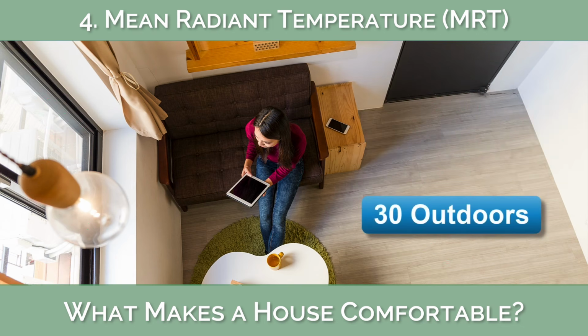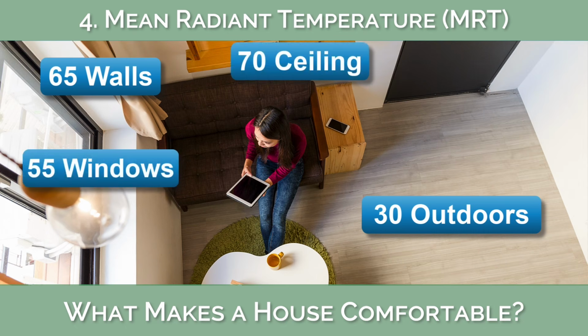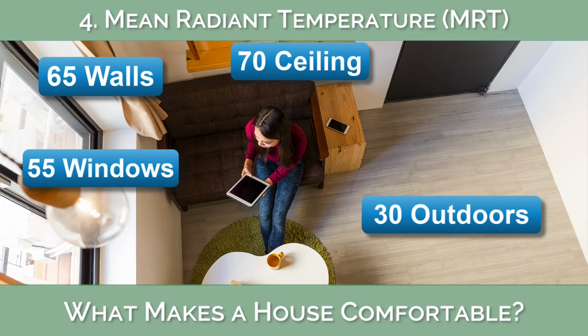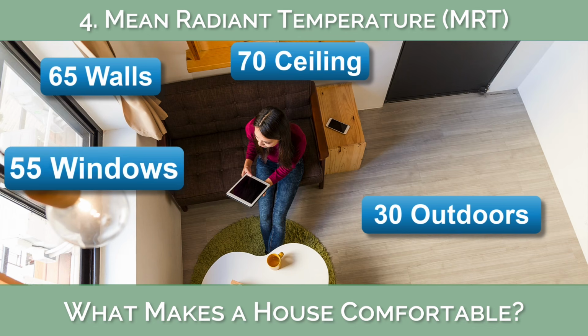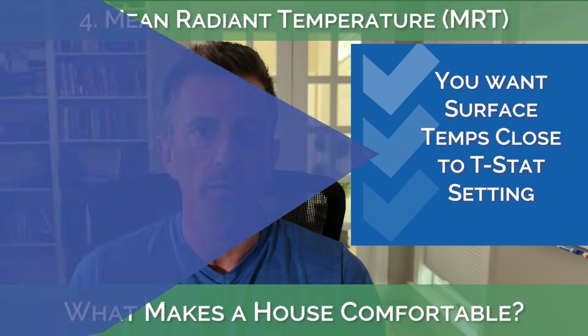Let's say it's 30 degrees outdoors and the surface of your exterior walls are 65 degrees, your ceiling is 70 degrees, and your windows and door surfaces are 55 degrees. Now, without getting overly complicated here, just understand that if the windows have more surface area than the exterior walls, then the 55-degree surface area of the windows will lower the MRT and you will feel less comfortable. So the main idea here is you want to avoid having surfaces in a room that are much warmer or colder than the thermostat setting that you want. Otherwise, you're going to be uncomfortable.